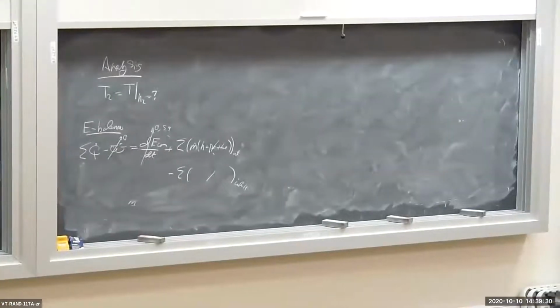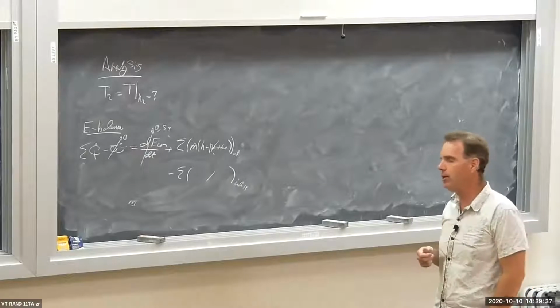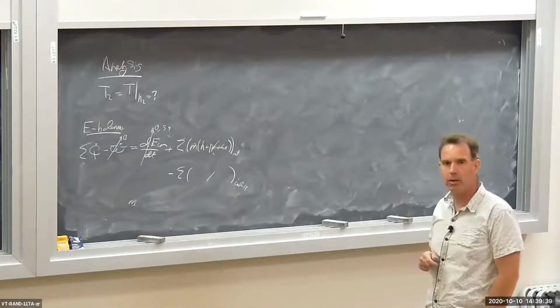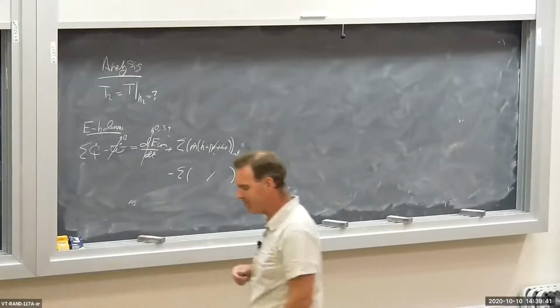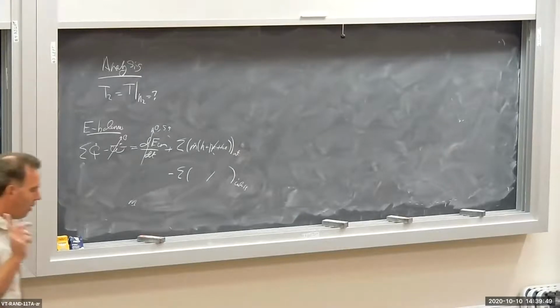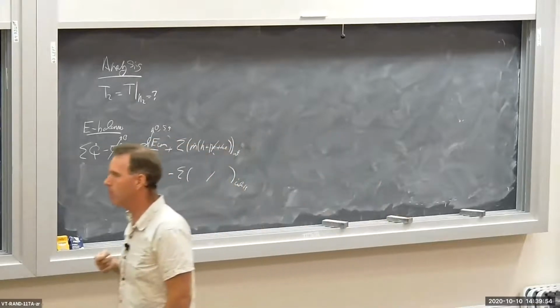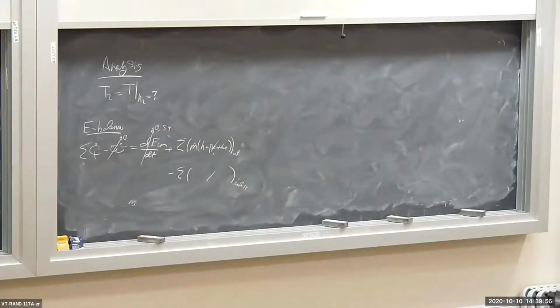By the way, if we were dealing with something like water and there was a major height change, maybe we were dealing with a dam where the height change is perhaps 100 meters, and it was water with a density of 1,000 kilograms per cubic meter, you might have a significant change in potential energy, but this is air. Air has a density of about 1 kilogram per cubic meter, and I don't see any indication in the diagram that these have any height change whatsoever in this problem. So potential energy terms are gone.